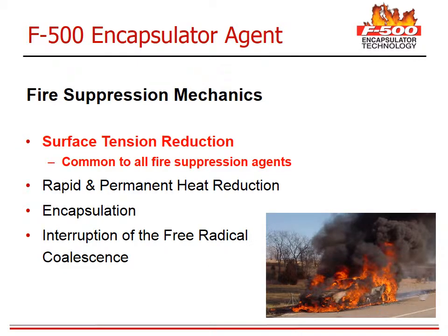Therefore, the first fire suppression asset is the surface tension reduction. This is the breakdown of the high tension of the water droplet, allowing for more surface contact area with the same volume of water. Imagine the droplets spreading out when F500 is added to it.